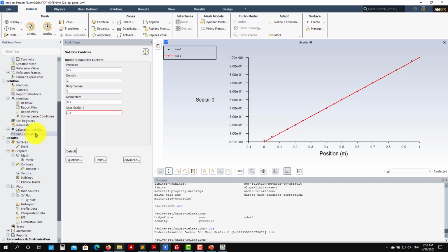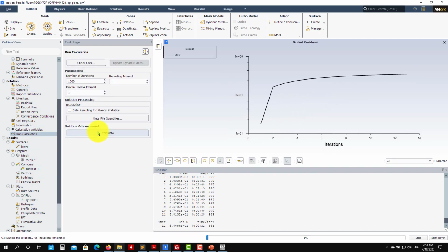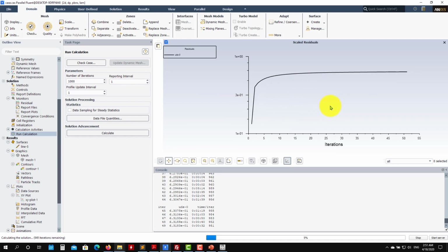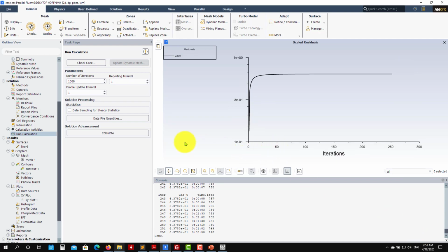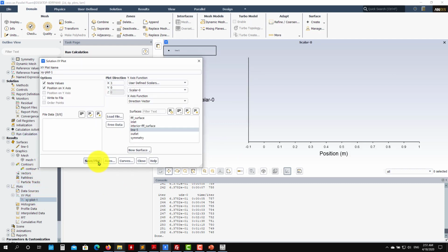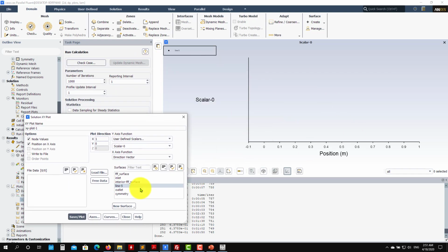And now as you run calculation, see that it's not converging. Okay, so it'll remain here stalled. You can leave it there up to 10,000 iterations and it won't do anything. In theory, you may imagine that it will go faster, but no, it's not going faster. So be careful. Do not over-relax. And actually, it's diverging. You don't have any value there.